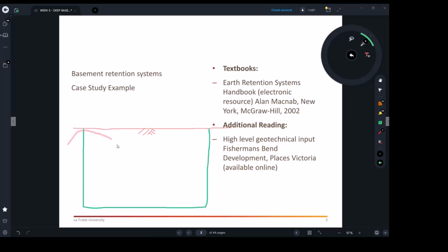Now, there's going to be a soil report which will tell you how critical it is. If it was rock, it is kind of cohesive. It will be sticking to itself. However, you can't find rock all the way 10 meters down from the ground. You always get, even if you have some floating rocks here, some clay there or sand. So usually you got sand and fill on the top, so it's not stable.